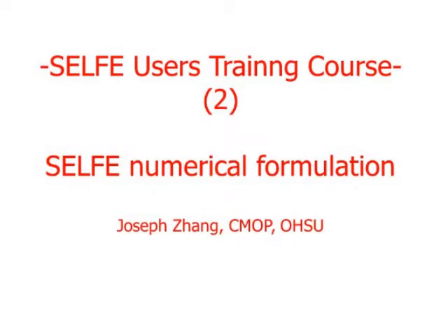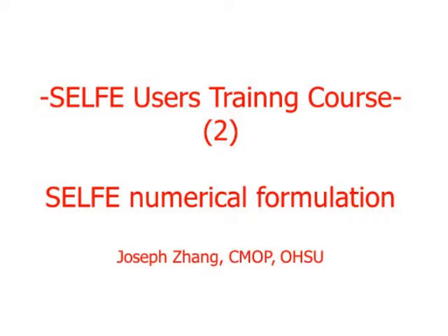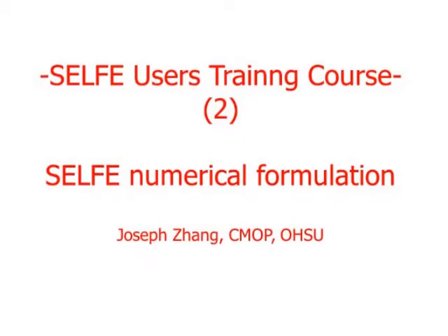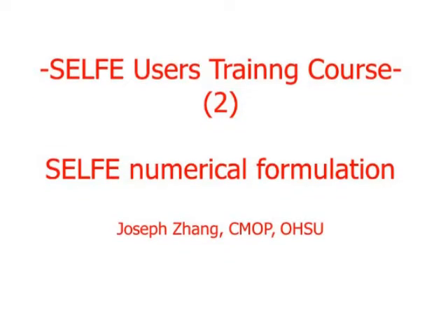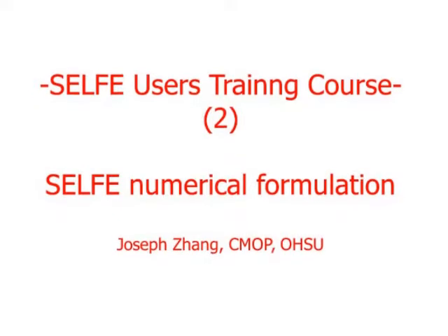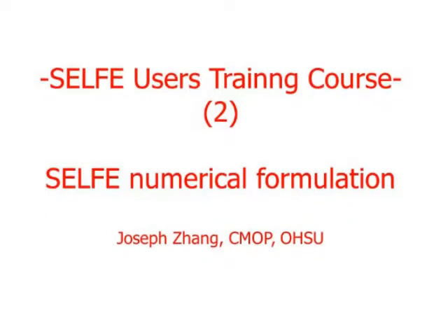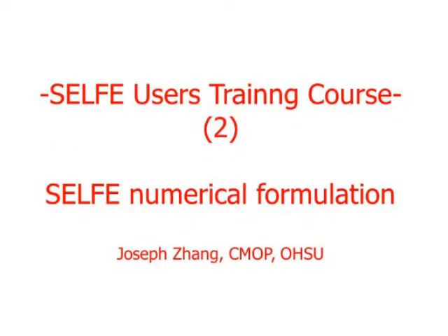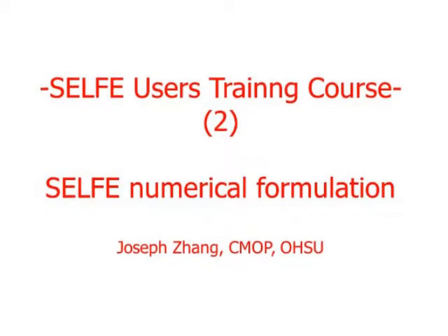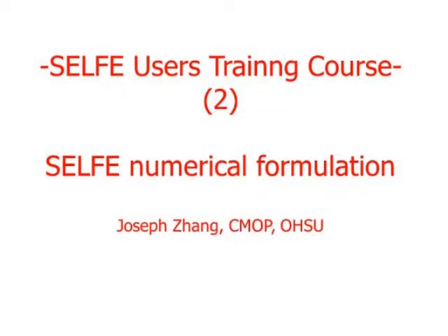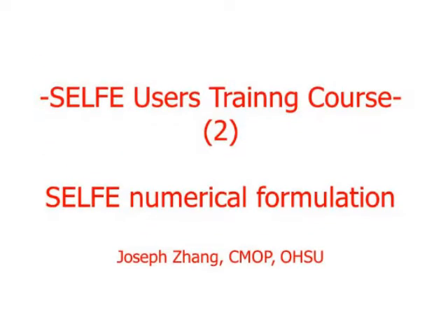So the way the ELM method works is like this. You basically solve this equation dx dt equals the velocity, okay, the 3D velocity, backwards. You integrate this differential equation backwards in time and space. So for example, you start from a side center at t plus delta t, and you try to reconstruct the fluid path, or in ELM terms, characteristic lines, backwards in space and time, and try to find the originating position at the previous time step t.